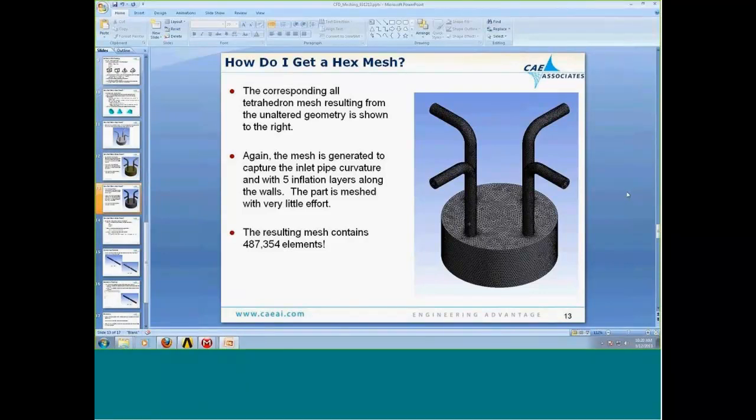Now, there was very little effort on my end to create this mesh, but the solution is going to take 4 times longer to generate. So if the solution is complicated, or maybe I have to run a number of different iterations on the boundary conditions, the savings in the mesh are going to grant me a great deal of flexibility when it comes to the solution time.